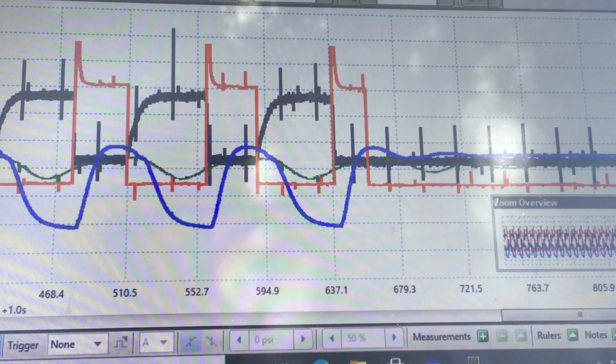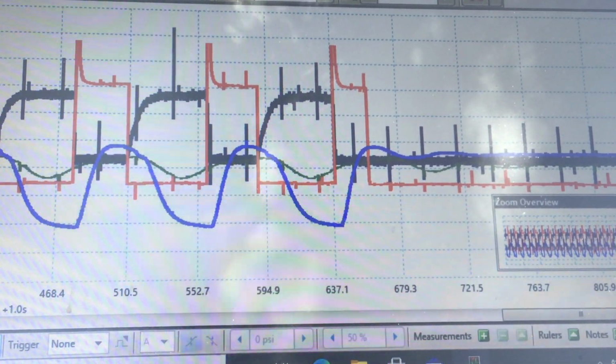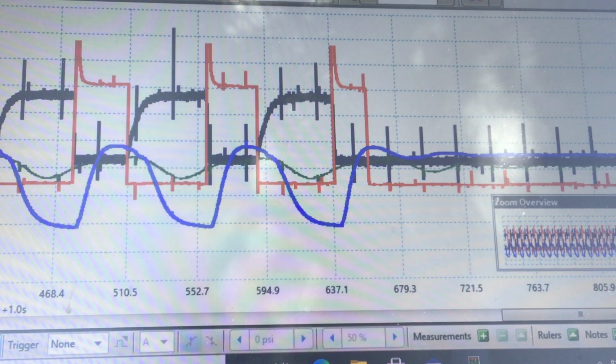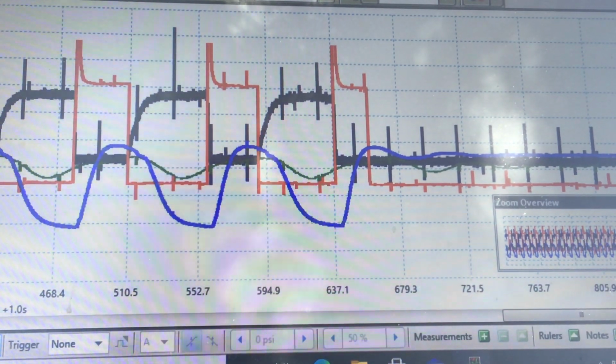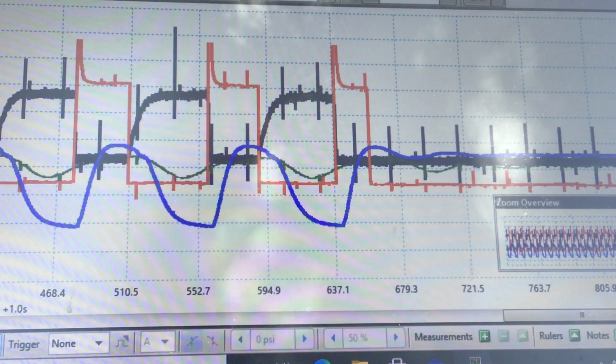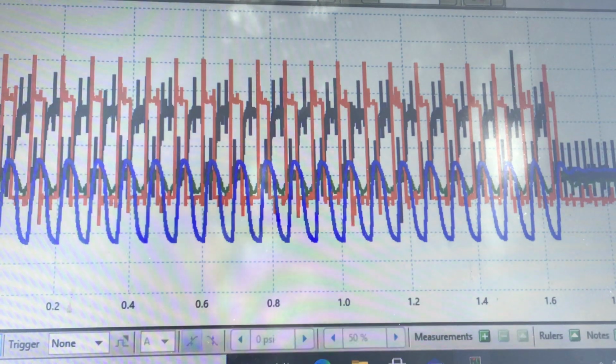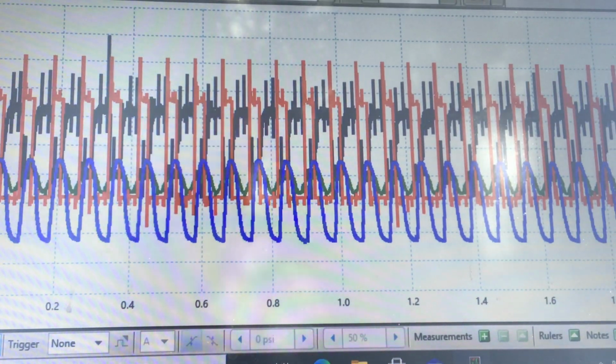If we had a physically leaking purge solenoid, we may see vacuum in a case like this. Just something to bear in mind, so we can pretty much say that this purge solenoid is not leaking, it's not flowing vacuum, and it's not commanded to do so. Nonetheless, we'll go down the line and take a look at some others.